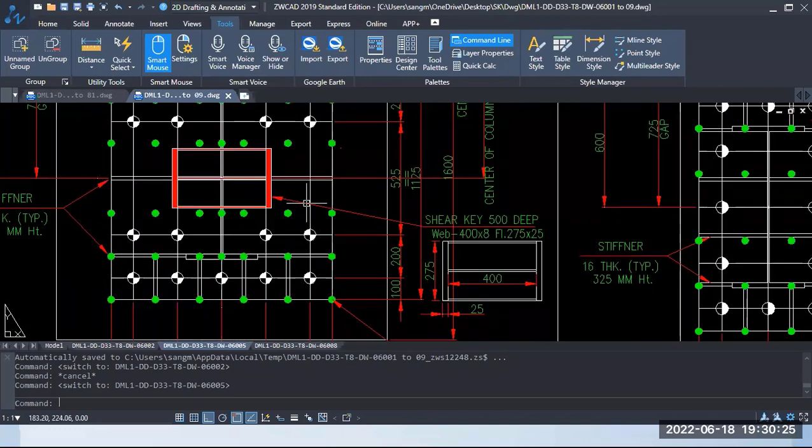We can transfer shear force in the base plate either through anchor bolts, or through the shear key, or by friction between the base plate and the concrete. But when there is a huge force, in that case we don't recommend, and the code also doesn't recommend, transferring the forces that way.